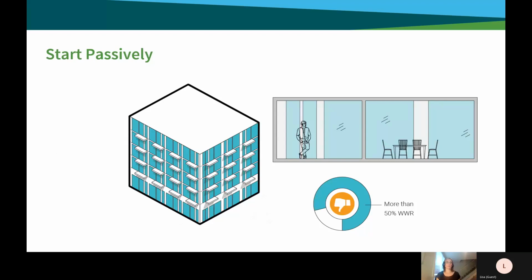The second passive design strategy the guide supplement outlines is to identify an appropriate window-to-wall ratio, or your glazing strategy. Lower window-to-wall ratios can reduce solar gains in the summer, which is good, and since glazing often has lower insulating properties than opaque assemblies, it can also help to reduce heating loads in the winter. To maximize your control over heat gains, south and north facades typically should have or can have higher window-to-wall ratios than on the east and west facades. Again, this will depend on your particular project and your context that you're working in.